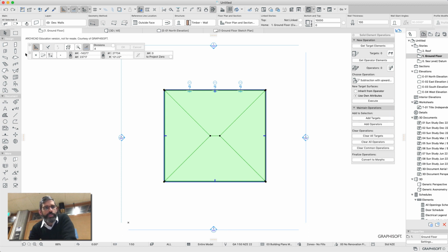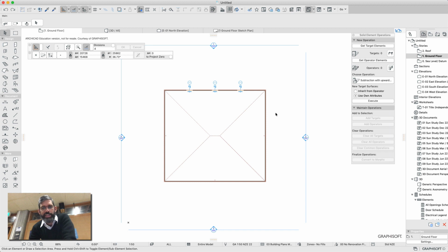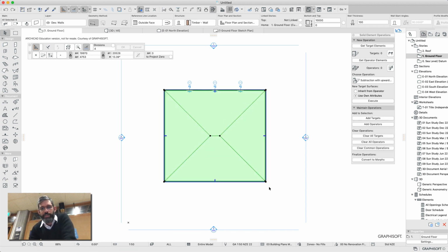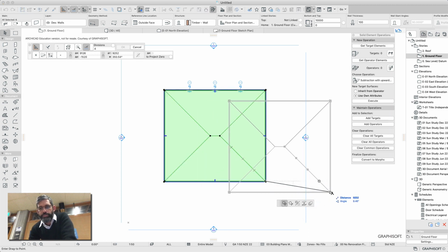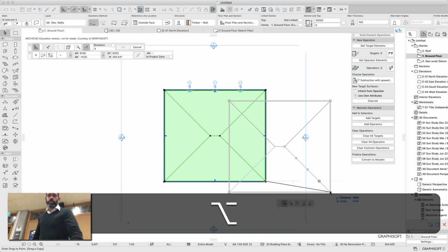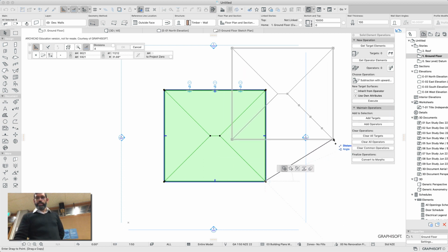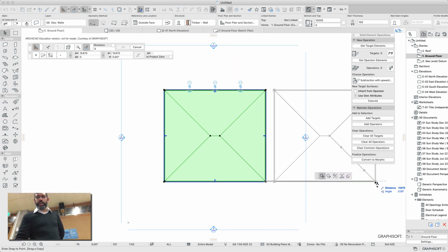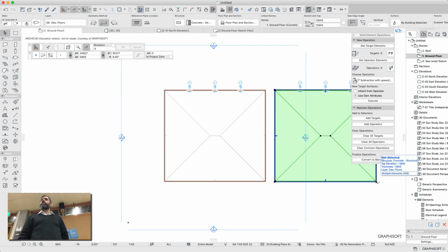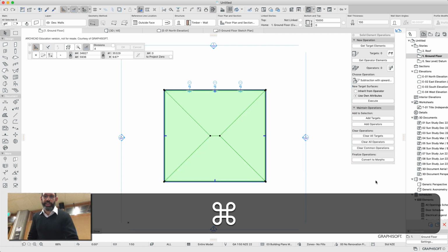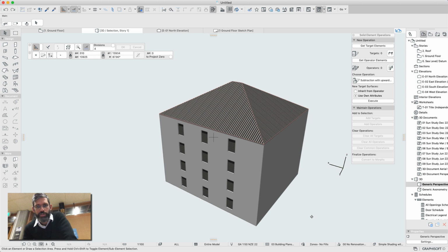All right. So what we're going to do is I'm going to duplicate this building, right? I can do this either in the 2D view or the 3D view. And it's actually a really easy way to do it. If I select everything and I go to drag it, I'll move it, right? But if you touch the Alt key, or the Option key in my case, you'll see a little plus appears next to my cursor. Remember, everything's all just like single clicks. Okay? See that little plus? So that means it's going to drag a copy. Cool, so now I've got 2 copies. I'm just going to undo that, and I'll do it in the 3D view so you can kind of see how it works in the 3D view.